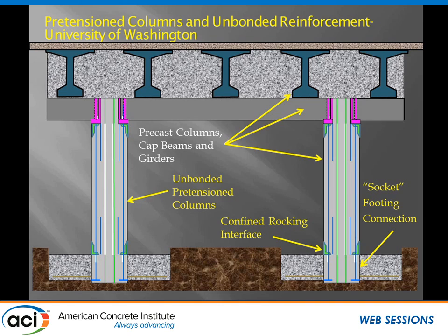Well, if it's good for pre-tensioning and post-tensioning, it should be good for conventional reinforcement. So the conventional reinforcement also crosses this interface. And in that area, we're also unbonding part of the conventional reinforcement. So there's unbonding in the pre-tensioning reinforcement and unbonding in the traditional reinforcement. So when these specimens show up at our facility, we're casting the footing. This is traditional cast-in-place concrete for the footing. And then in this case, we're actually pre-casting the cap beam also. So the system is put together, which makes it also effective for accelerated bridge construction.